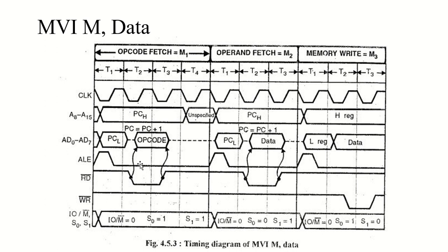One interesting thing which I want to point out is that the opcode fetch is using the program counter to fetch the opcode from program memory, right? Let's say it is holding 36H. The operand fetch is very much similar to a memory read. You can also call it a memory read cycle, right?